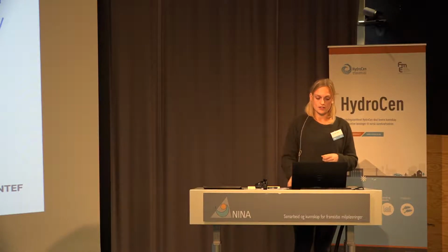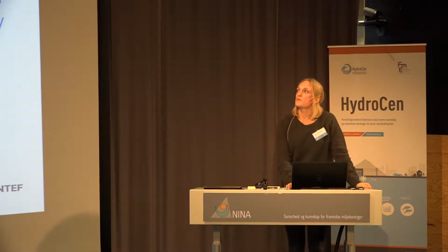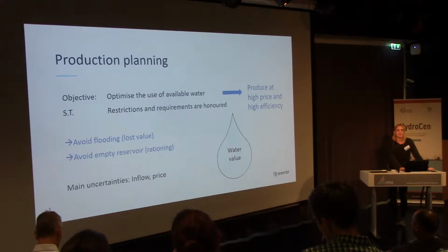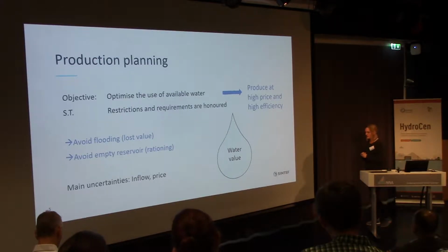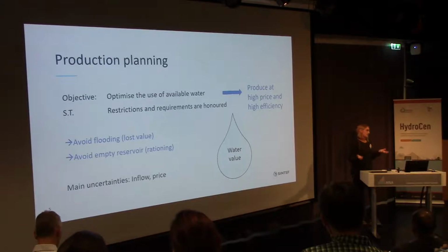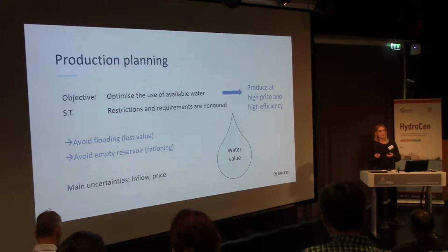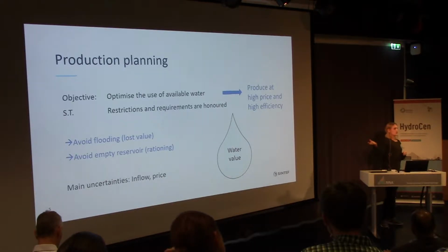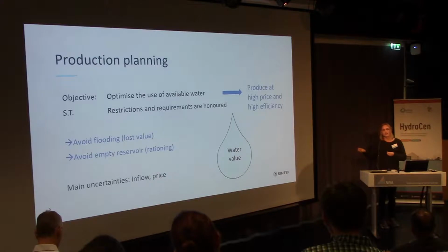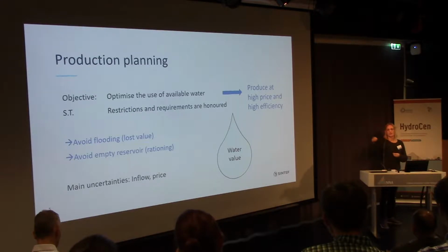So the main uncertainties are inflow and price. And we talk a lot about water value. And that's because I can produce today and I will get a price, right? But what's the value of storing the water? That's why we talk about water value and why we calculate a water value. That's the value of waiting, of storing it and using it for another time, in a later period.